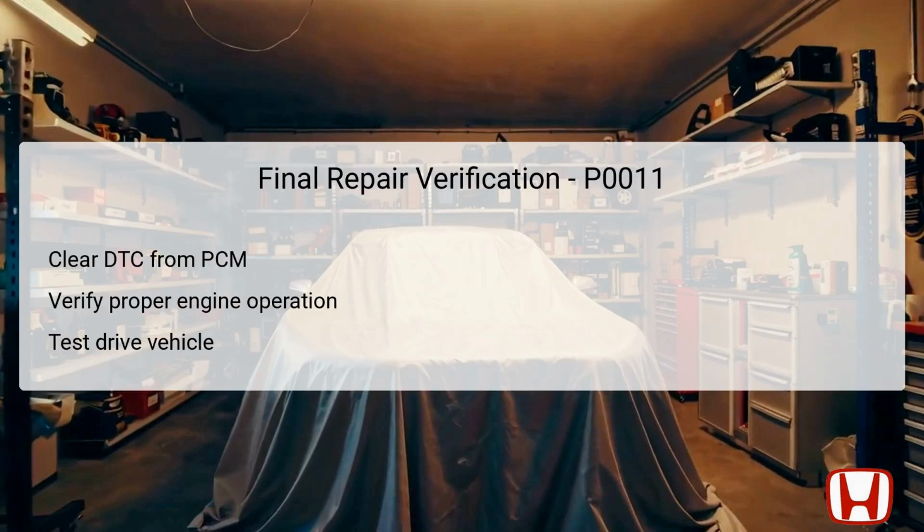After completing the necessary repairs and replacements, the next step involves final repair verification. This process begins by clearing any DTCs from the Powertrain Control Module (PCM) to reset the system. Once the DTCs are cleared, it's crucial to verify that the engine operates correctly. This involves monitoring the engine in different operating conditions to ensure that no new trouble codes are triggered and that there is no abnormal performance.